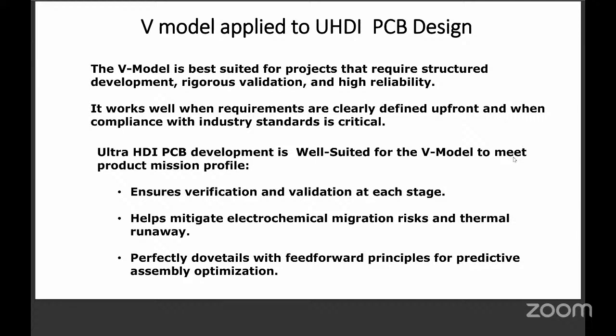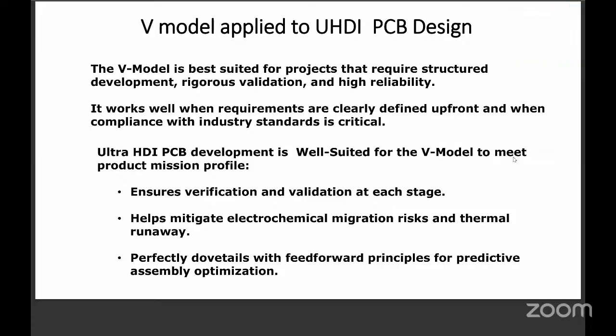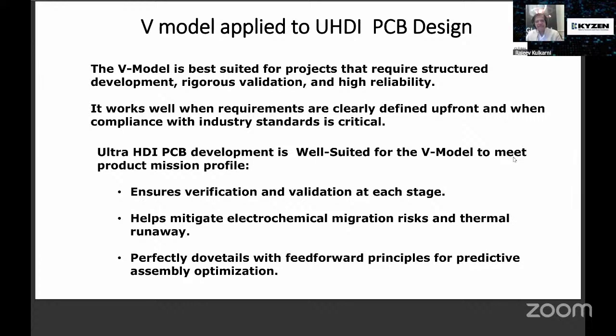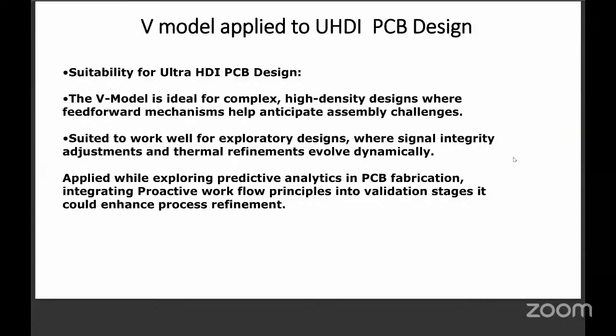And Ultra HDI PCB development is well suited for a V model to meet the product mission profile. You should know the mission profile upfront. It ensures verification and validation at each stage, and helps mitigate ECM. ECM is electrochemical migration, which we covered a couple of months back, and is still a major threat. And thermal runaway. Again, your favorite subject, thermal, is coming back. Things may get too hot. The V model perfectly dovetails with feed-forward principles and predictive assembly optimization. If you are using AI, you can predict what is going to happen. Feed-forward is much more important. Please go to the next slide.